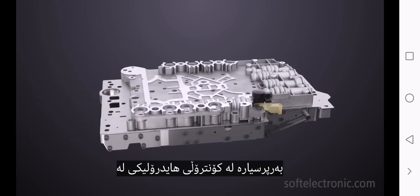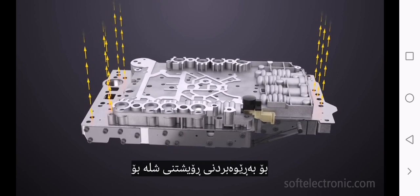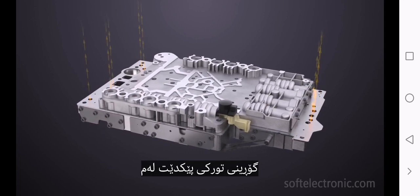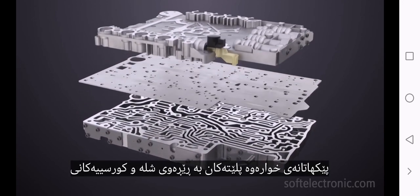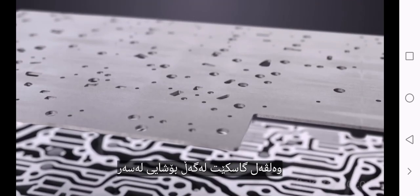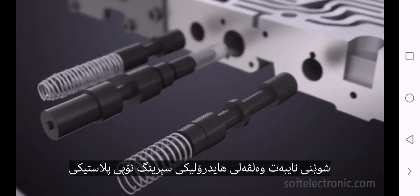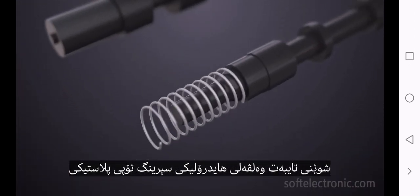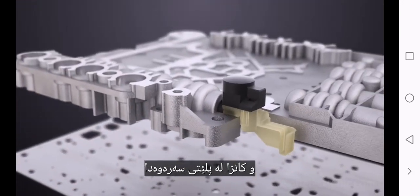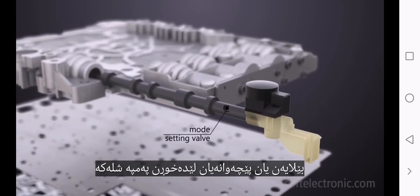The valve body is responsible for the hydraulic control in the automatic transmission. Its role is to manage the fluid flow to the various sections of the gearbox and the torque converter. It consists of the following components: plates with fluid paths and valve seats, gasket with gaps on specific places, hydraulic valves, springs, plastic and metal balls. In the upper plate is the manual valve, which determines whether the car is in parking, drive, neutral, or reverse position.